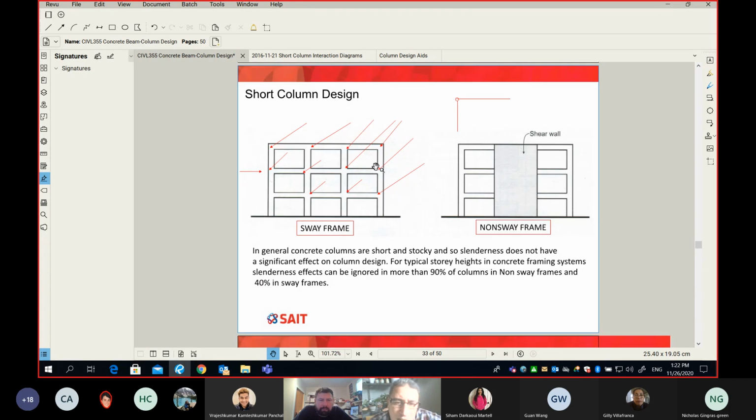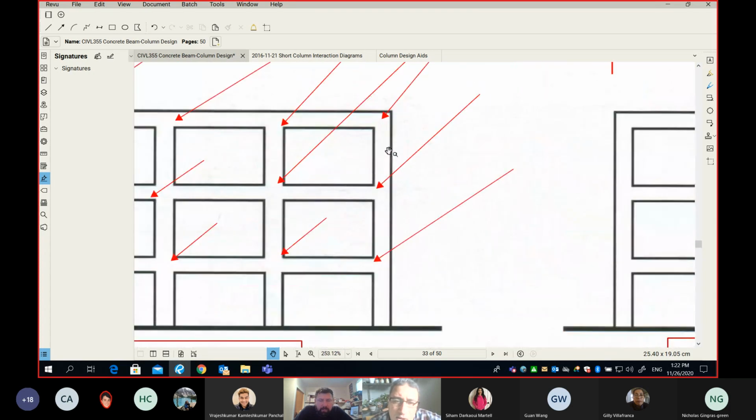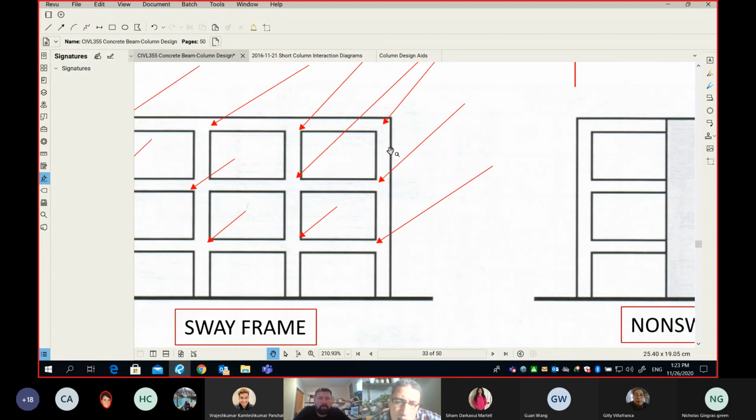In terms of concrete, the column bars will have to extend and go into the beams. Not only like I showed you before, where the column bars go a little bit inside your beam, but not necessarily bend and go enough distance into your beam.